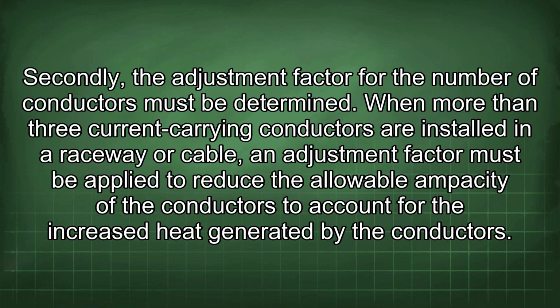Secondly, the adjustment factor for the number of conductors must be determined. When more than 3 current carrying conductors are installed in a raceway or cable, an adjustment factor must be applied to reduce the allowable ampacity of the conductors to account for the increased heat generated by the conductors.